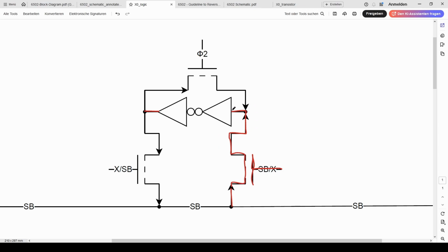It might not be a nice, steady, unambiguous 5 volts. Or at least, I guess it should still be fairly unambiguous, but still, it's a good idea to refresh it. And so instead of just putting it in directly, it controls a NOT gate, which basically has its own power supply. And because we don't actually want to invert it, we just invert it again, and then we get this output.